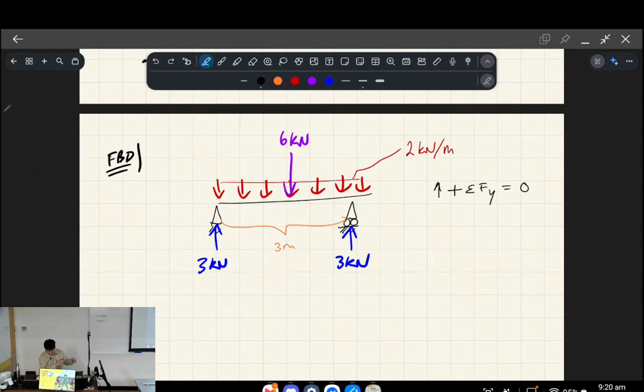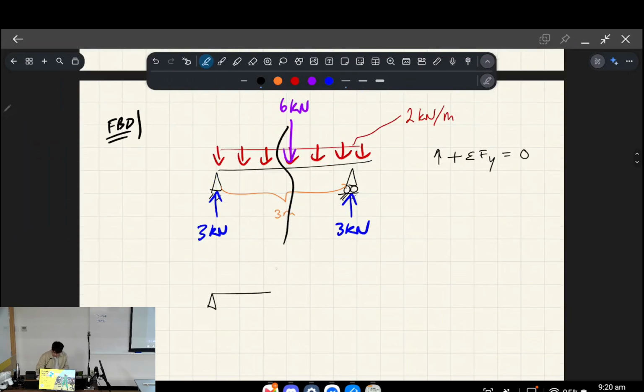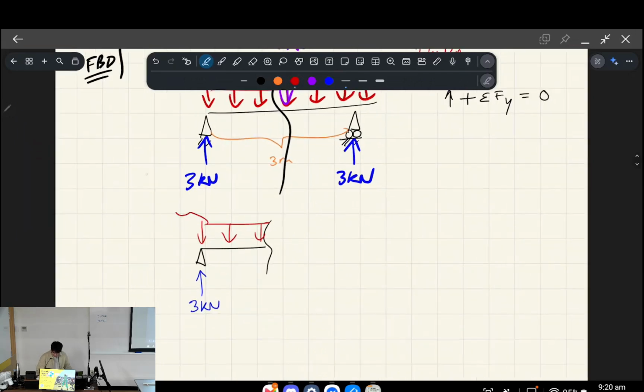If instead we change the camera angle, quote unquote, so that it only captures, let's say, that portion of the beam, then the forces should still be in equilibrium, and therefore the beam should still not be moving. That's essentially what happens when you slice or cut a beam. So let me redraw this slightly. I'm drawing roughly half the beam, and I'm showing you part of the distributed load that we've got, and we've still got that same reaction. And then this is 2 kilonewtons downwards per meter. Okay.